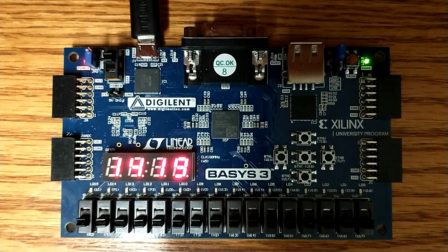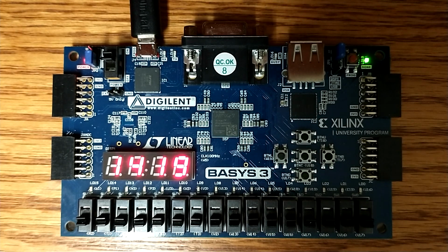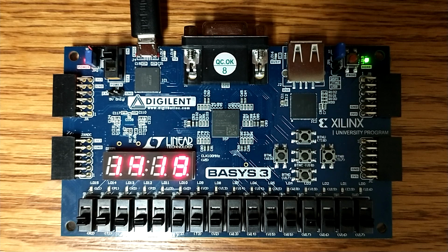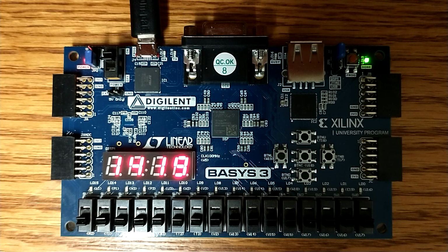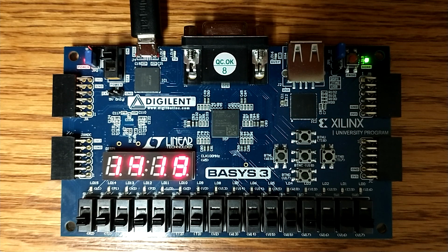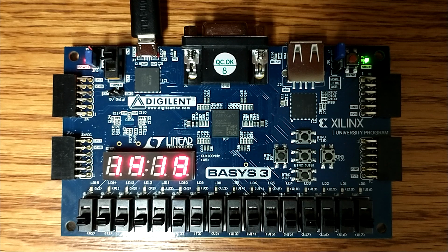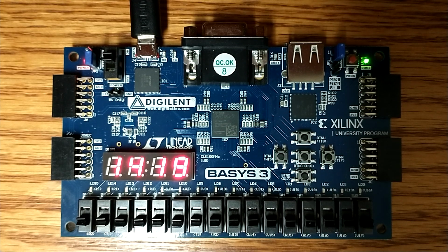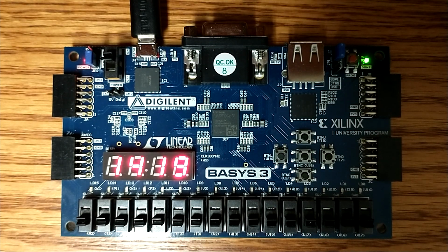It's counting up in hex, so what looks like a 14 over here is a 20, which is exactly what we want. That's the number of debounced button presses that it registered. And then we have a 19 on the other side, which is a 25. So I believe one of the debounces in there might have registered 2 extra values, so I believe it only bounced 4 times, which is about a 20% rate. And again, I've seen it range a little bit, but between 10 and 20% is usually where it ends up.